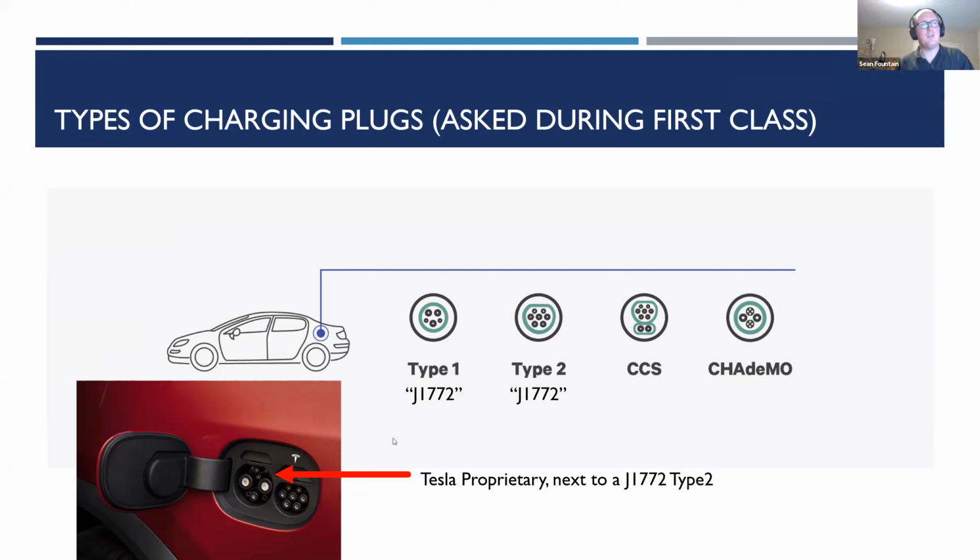And now Tesla is starting to use the CCS on their vehicles and offer it on their charging stations as well. So there's a unification happening. But you can always charge at home or at the mall or wherever at a non-fast charge rate. Anywhere you go in the world will have J1772 as a standard. And the 110 volt plug adapter that comes with your car will be a J1772 adapter.